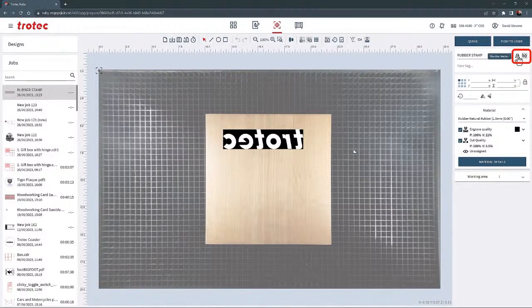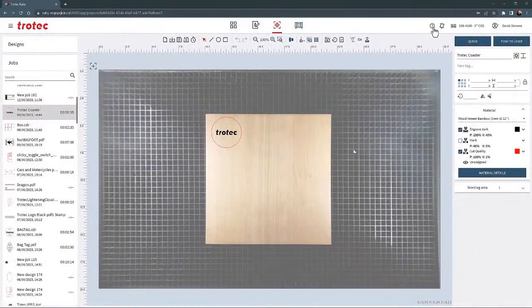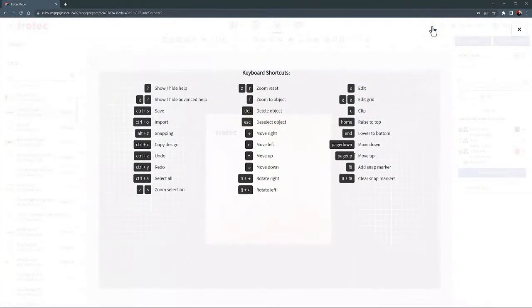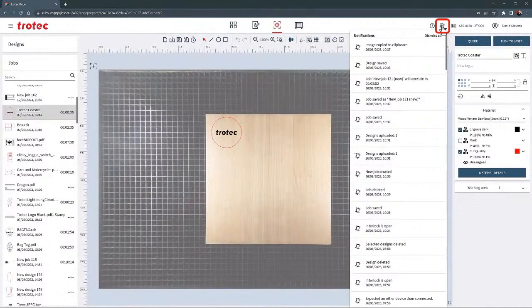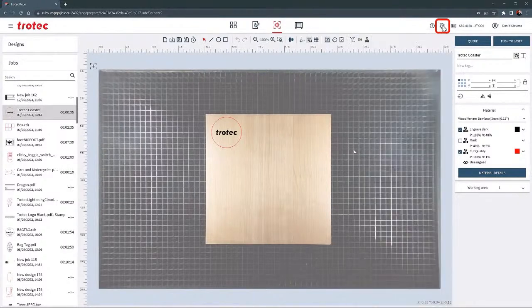These other tools will allow a rubber shoulder angle to be selected: flat, medium, and steep. If a rubber stamp is going to be cut out, links can also be turned on and off here. Links are small tabs that are applied to the cut that will hold the rubber stamp in place, so many stamps can be cut and removed at once, cleaned, and then broken away from the main sheet after cleaning. The small question mark at the top of the page will show all the keyboard shortcuts for the prepare screen. The small bell at the top of the screen will show all notifications.